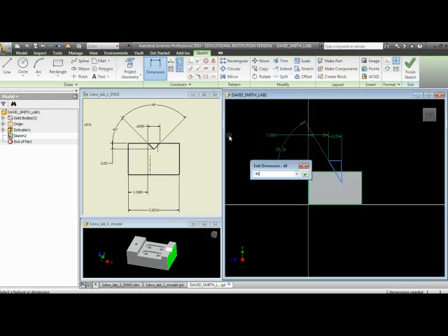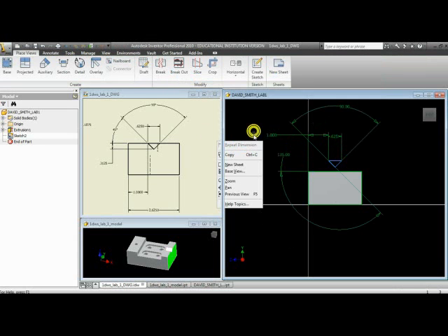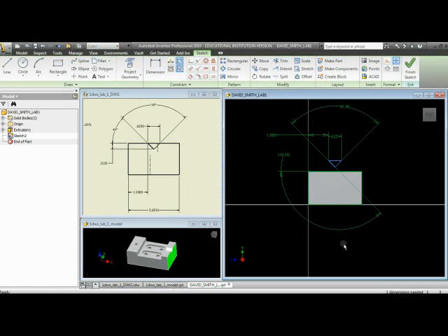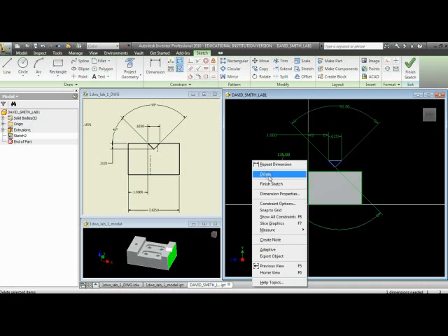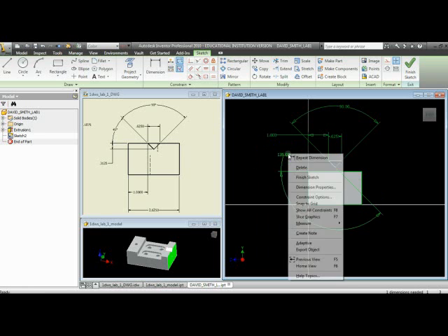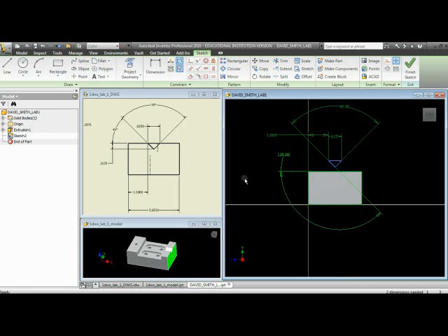Okay, so I'm going to create that V shape, and to do that I need to actually create a sketch plane on that green face. Now I can leave that green and hit create 2D sketch, and it will automatically jump to that, or I can hit 2D sketch, pick the face, and we're ready to start drawing that now. What I like to do is go to that view and look straight in on that view, and I'll draw some lines here to make that triangle or something similar to what I want there.